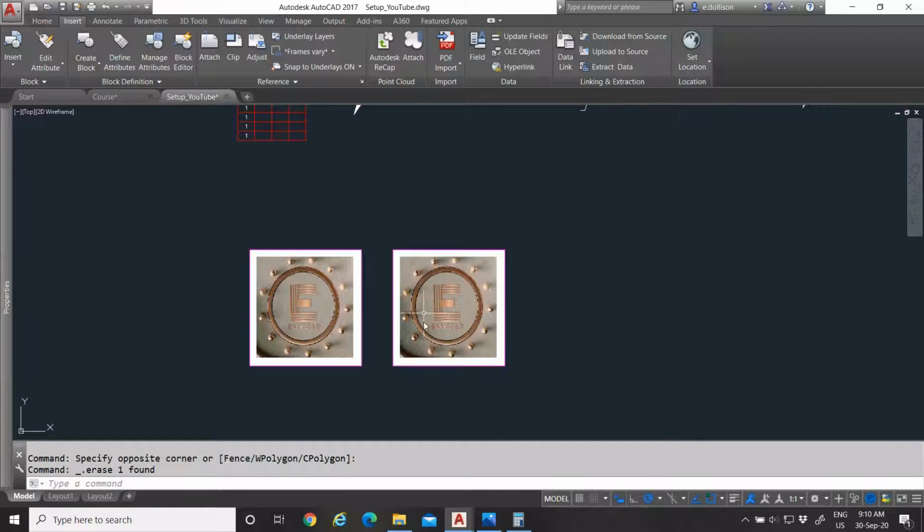If you want a real image, that's how. But of course there is one more way. The way I like to do it is by drawing my own logo within AutoCAD. That way I will never have an issue looking for my logo, and my logo will be within my drawing as a block. You can also export the block so that you can insert it in multiple drawings.